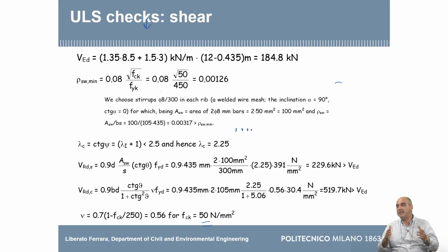That is an easy way. Basically, you put 3 stirrups per meter. So we comply with that. This is not a very shear sensitive structure. For this reason, you just need the minimum reinforcement anyway. But then with this value, okay, you end up with something. How do you estimate theta?